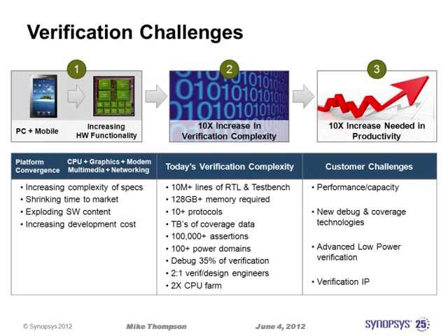Another challenge, sorry, I forgot this slide builds, is verification, which is a huge deal in an SoC today. We spent about 200,000 hours verifying just the audio subsystem. So 200,000 hours of server time verifying the subsystem. Now, we have a lot of configurability in there and things that we had to look at, which you probably wouldn't implement in your own solution, but it does make it much more reusable. It spreads it across a lot bigger application domain, so it's easier for you to use. Even so, the verification effort inside of SoCs today is becoming enormous.